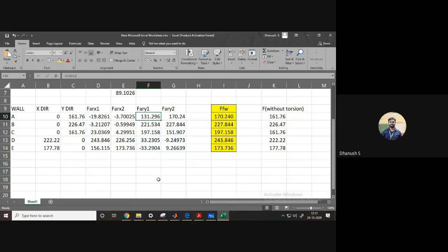In this case, fortunately for us, all the values that are greater are positive in nature, so max also worked. So use the absolute maximum of all the 4 cases. List them. That will be your design forces that you'll have to consider for shear wall design.